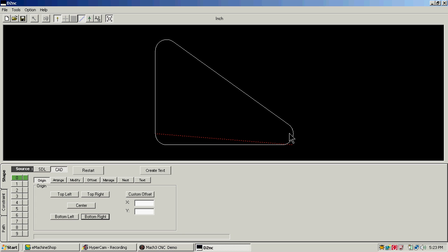Whatever you were originally lining up when this was flipped over this way is now also the same 0, 0 point that you're lining up to machine this part in the opposite direction. If you own a big old Haas machining center, I don't think you'll need to do that, but for my uses, I just do this as a safe practice to make sure all my holes are going to line up, everything's going to line up. I'm going to always move my original 0, 0 as my starting point. So that was the point I was trying to make there.